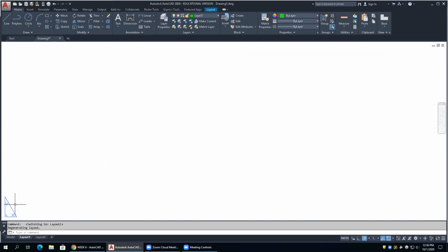Okay? What we have to do is we have to rip a hole in our paper so we can see in the model space. So it's kind of like, I want to see out that window over there. I punch a hole through the wall and I can see outside. All right? So the hole we're going to punch through is called a viewport. And the viewports, usually you just kind of pick them where you want them. I have really valid coordinates for you. You go to the second sheet of my handout, the second sheet of the stapled handout. You'll see it's kind of hard to read, but I have coordinates there, lower left, upper right.